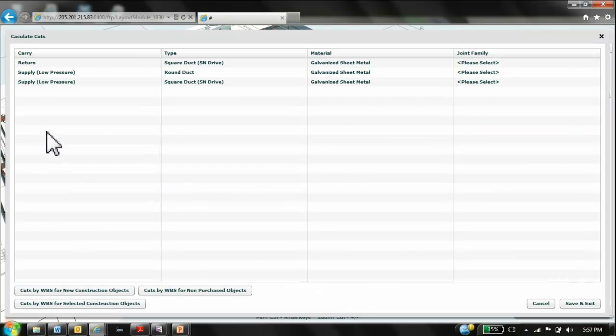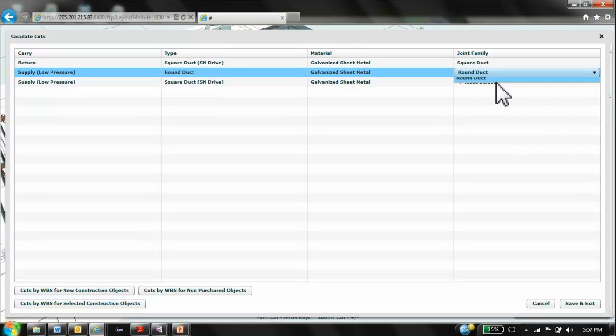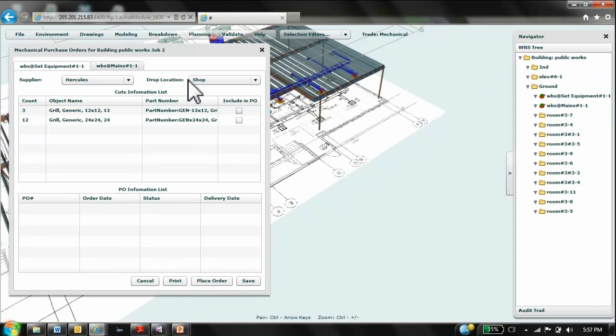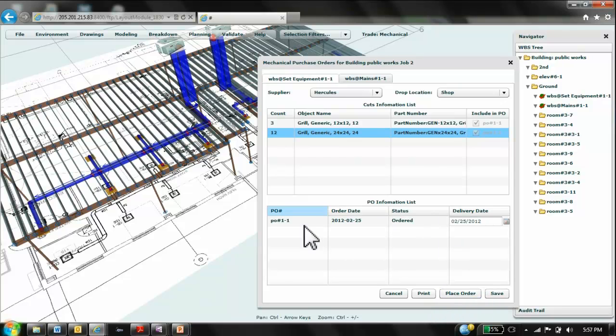The final process that can be achieved with this model is to create a bill of materials. The user must select the types of joints that are proposed to be used and calculate full material lists for each of the work breakdown structures, shown here in separate tabs. These material counts can be used to create purchase orders and set up just-in-time delivery, which will drastically reduce material handling on the job. Material is moved an average of 4 times before it is installed on a traditional construction project.